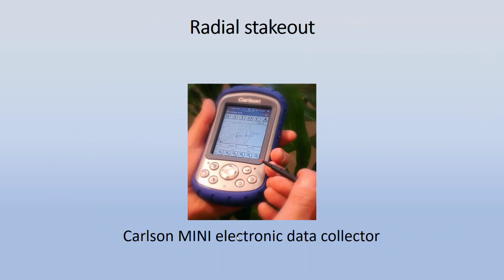I'm going to have you go through those calculations a little bit for homework just so you're familiar with where they come from. But nobody does this in the field in practice, and I'm not going to make you do it in the field in practice either. We're going to use electronic data collectors, which use the coordinates that we're going to upload into the job file, and they'll compute the angles and the distances that we need to lay out with our total stations to place that point in the ground where it needs to be.